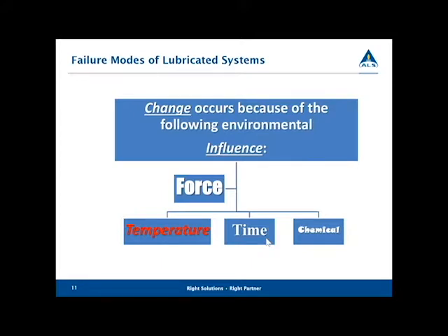When we think about force, it comes down to thinking about how the machine is operating in its given process. It's designed to do something, but if for whatever reason the productivity requirement is increased, you're actually going to be increasing force, and componentry is going to break. Temperature can work the same way. Obviously, the more we run a machine, the hotter it's going to get. That increases temperature, and with temperature brings about a whole host of other problems.